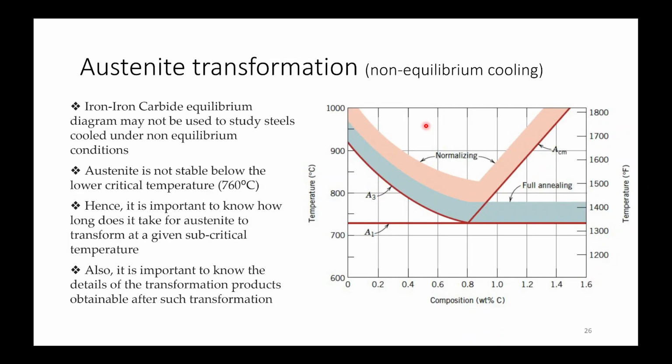So how you can convert your cooling curves into phase diagrams. It won't tell you where the boundaries are. It will tell you what phases are present in these various phase fields. These are phase fields, these correspond to invariant lines, and these are invariant points. This is what is told in phase diagrams. Depending on the phase diagram, you can tell what your phase structure will be, like whether you are getting bainite or martensite. That will depend on cooling rate.